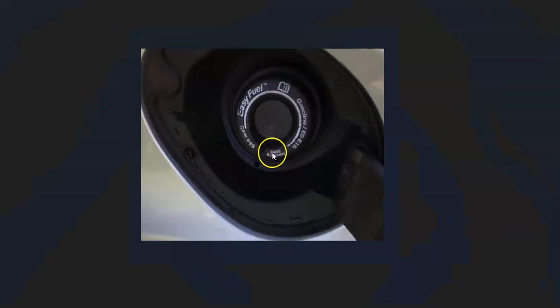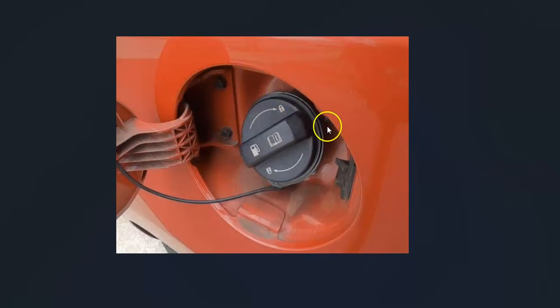There's some different methods for how you go about cleaning it up. Some people will spray like WD-40 right around here and wipe it off, try to get in there with a screwdriver and a rag or something like that. Other people will use compressed air. But the thing to go and check out is to see if this inlet is slightly open and causing an issue, or if you just got a bad gas cap, if it's cracked or not sealing properly, because a bad gas cap or fuel inlet can cause issues.